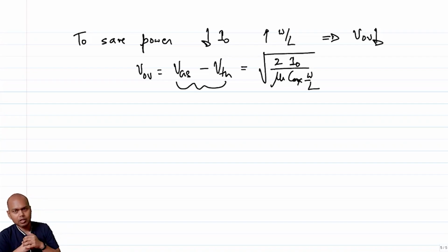We'll talk about distortion after we are done with a few more lectures. But for the time being, it should not be very difficult to understand that if the transistor characteristics itself is going towards the transistor turning off when the signal is swinging in one direction, and towards the transistor being turned on when the signal is swinging in the other direction, then obviously the resultant current that is going to come out will be distorted, right?